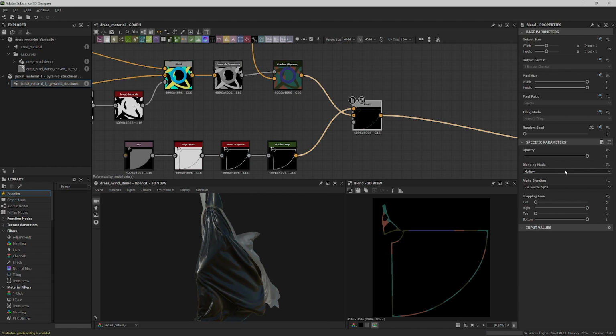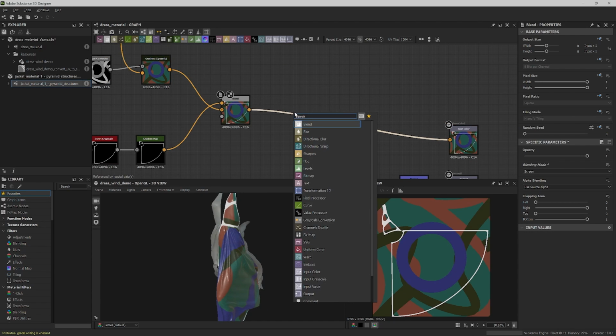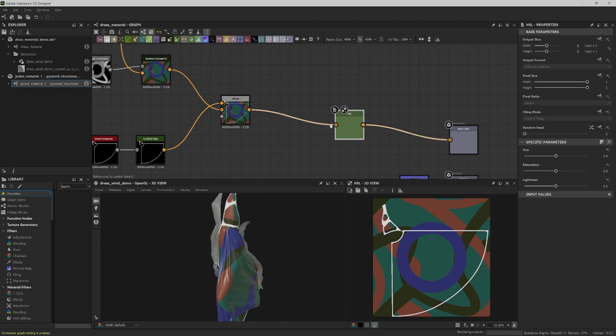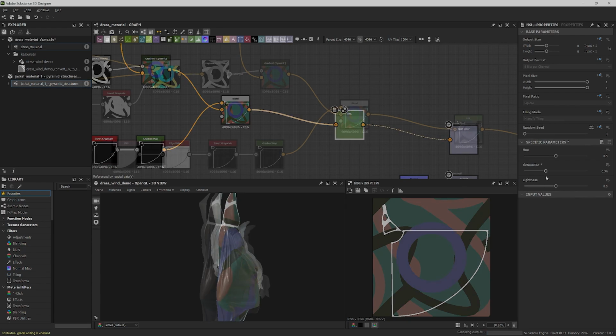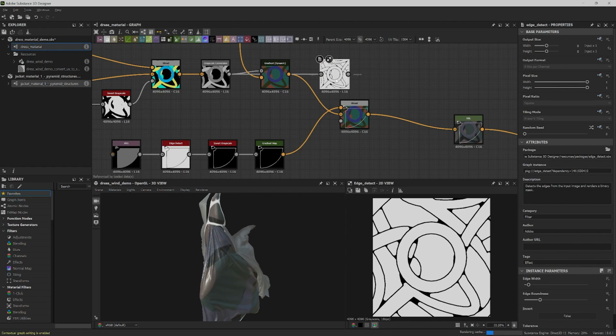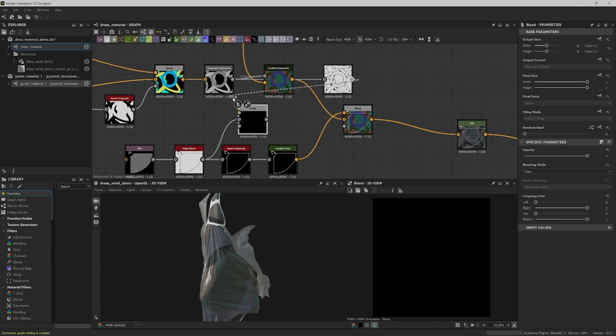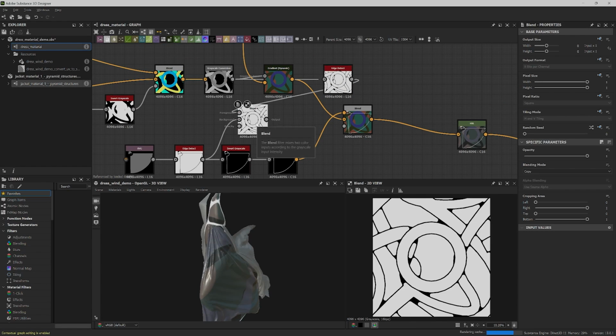And set the blending mode of the blend node to screen. Let's now reduce the saturation significantly to create more subdued dress colors that complement the jacket's tones. Take the grayscale conversion of the splines, plug it into an edge detect, and blend it with the edge detect of the switch UV mask. This connection integrates the 2 elements more closely.